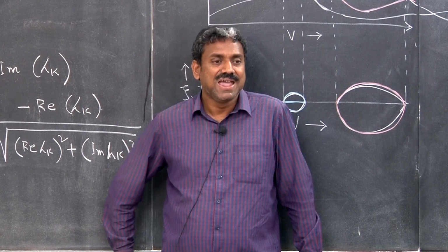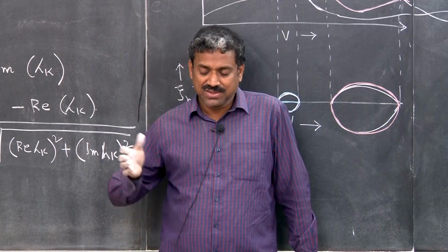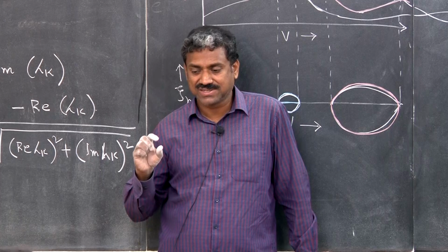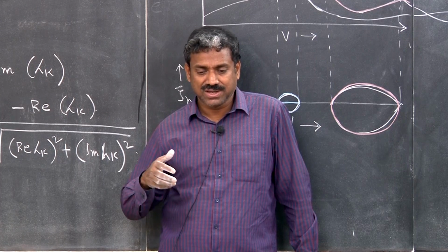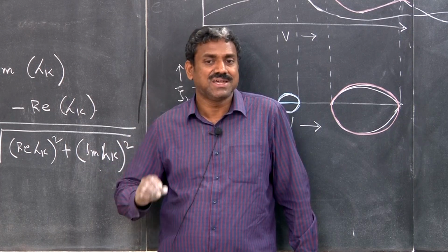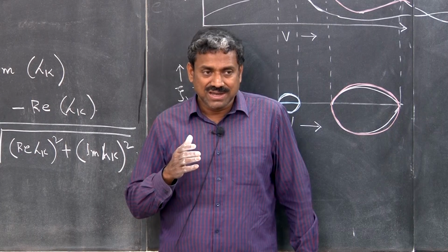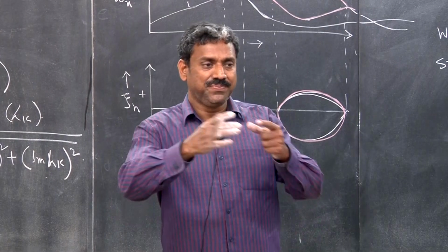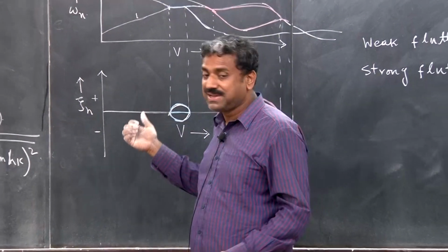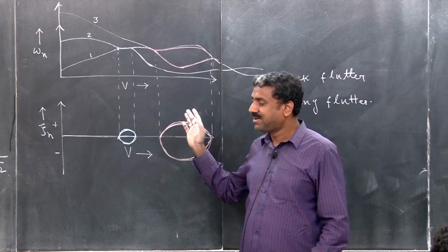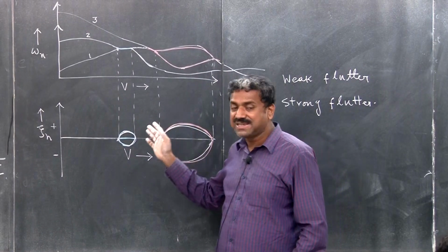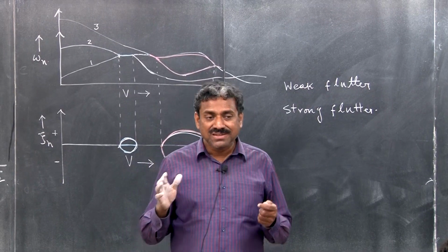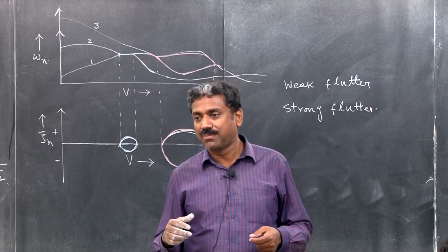So, you have to avoid that, and in design you want to push it away by modifying the geometry and things like that, or sometimes by artificial means, you attach some kind of strake or structure around the chimney, which will break the vortex structure, okay. Now for a chimney there is a basic difference from bridges. Bridges are basically streamlined objects, but chimneys are bluff bodies.